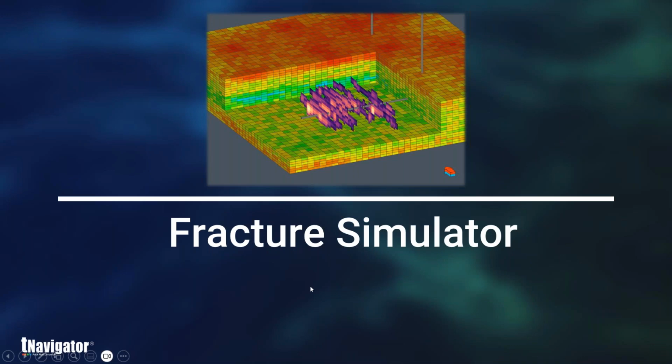So now that Zach has explained 3 of the methods to implement hydraulic fractures in tNavigator, I'm going to talk about Fracture Simulator. This is a product that calculates the propagation of the hydraulic fractures in the reservoir by considering rock properties, well injection regime, properties for the injection fluid and the proppant, and the interaction between the different fractures to account within the solver settings for the fracture propagation. This is a fully implicit method that jointly solves the fluid dynamics equations and the elasticity theory.